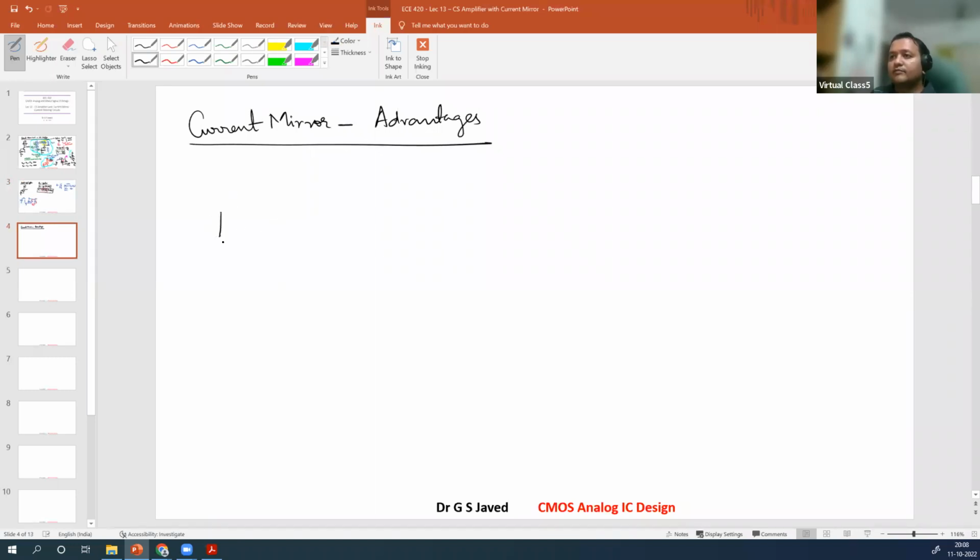For example, assuming you have one current mirror like this, it is important that the main current source will have the diode-like structure, right? You will have this diode-like structure, and this node is your VGS supply, which is common. Now this node, if you can distribute and ensure that the VGS supply of all these devices can be maintained,